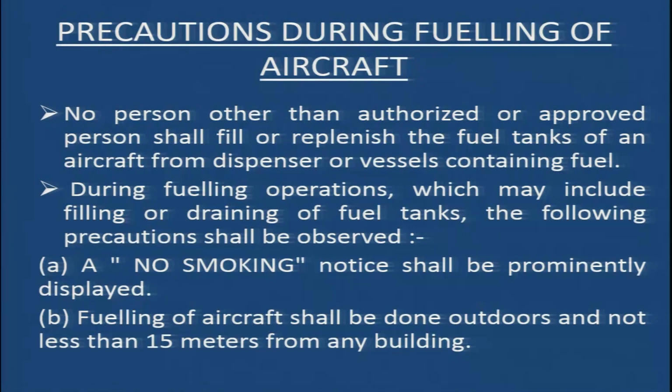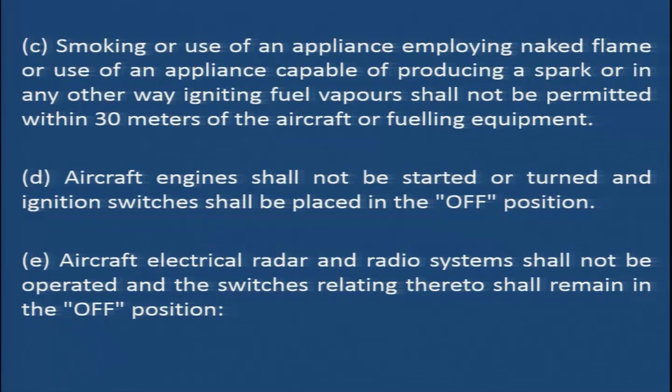Fueling of aircraft shall be done outdoors and not less than 15 meters from any building. So, a very important thing is that fueling should be done out in the open, and it should be at least 15 meters away from any building.